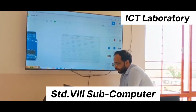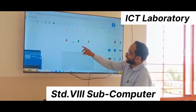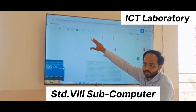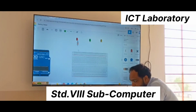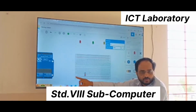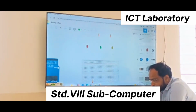At first, you have to place 3 resistors in such a manner that one terminal... actually, every component has how many terminals? 2 terminals. Here you can see 1 and 2, 2 terminals are there. Here also for the resistor 2 terminals are there. So for connections, you have to place one terminal of the resistor on this negative side of the breadboard, and similarly you have to place the other 2 resistors also on the breadboard.